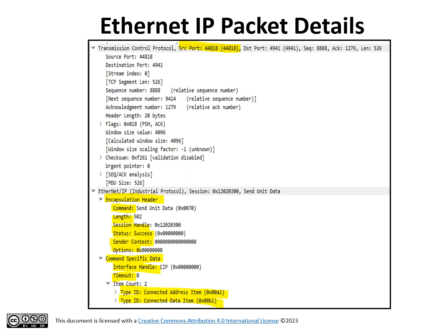A deep packet inspection of an Ethernet IP packet can be done skillfully by referring to the detailed descriptions of each of the encapsulation header and data fields in the previous section. As shown in the figure below, the source port set to the value 44818 indicates Ethernet IP running over the Transmission Control Protocol, TCP. Further, the sender context and option fields set to 0 indicates a normal transmission.